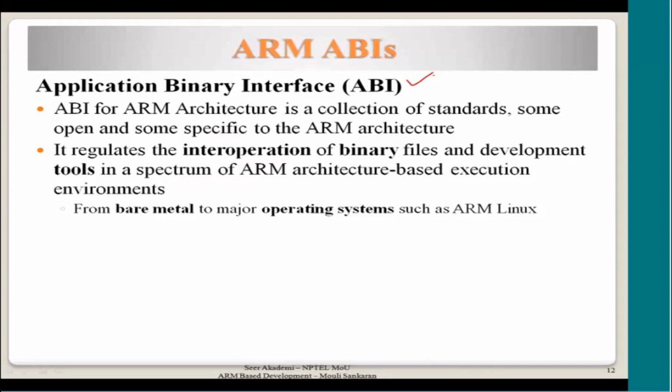So that is defined by these APIs, and then all the tool vendors will be following that. Now it would be useful from bare metal to major operating systems such as ARM Linux. So what is bare metal? Bare metal means that just the processor is there and memory is there, all the hardware is there. Okay, there is no OS running there.